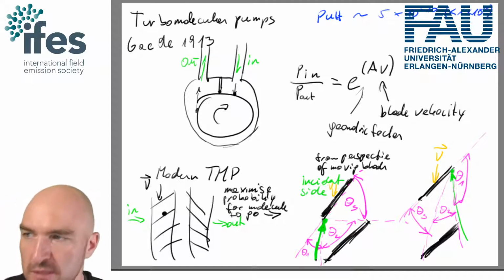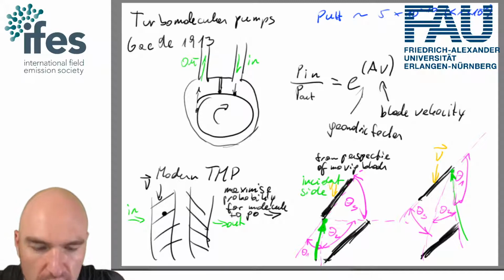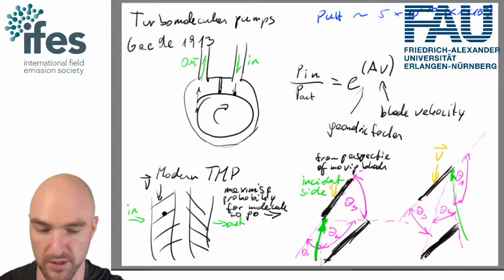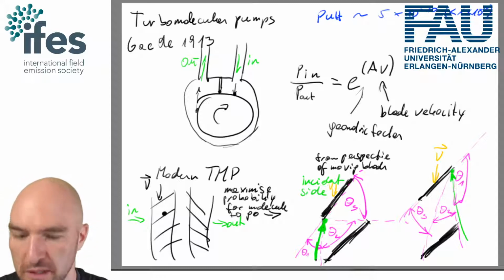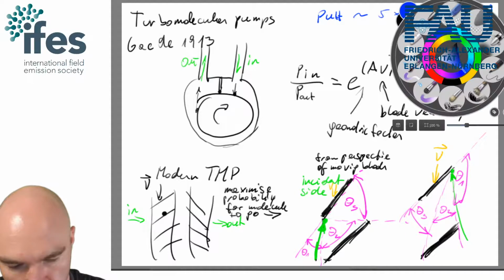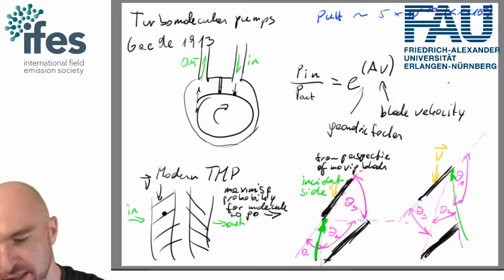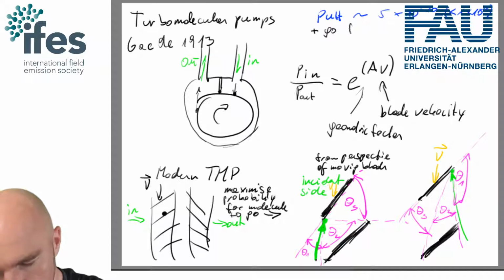I have one system that we operate that goes into the higher 10 to the minus 11s just with a turbo pump. Yeah? So that's all doable these days, and that's why I think turbo pumps are going to be the future for atom probe tomography, just simply because they have upsides. They can go from ambient to UHV.